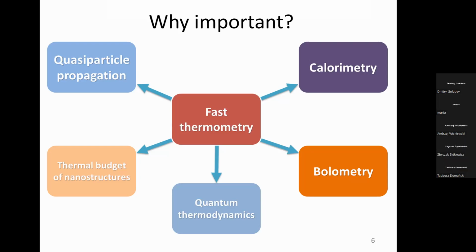So my claim is that at this very low temperature, it's very easy to overheat due to some dissipation which is intrinsically involved in the operation of the device. You can easily overheat the device, and if you neglect the thermal effects, your device may not work properly. So my thermometry could provide a diagnostic tool for better understanding of the thermal effects in such devices.